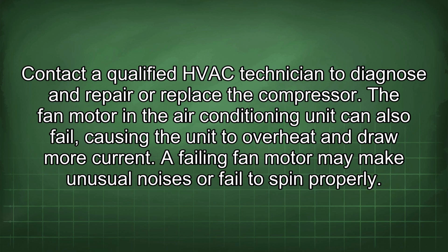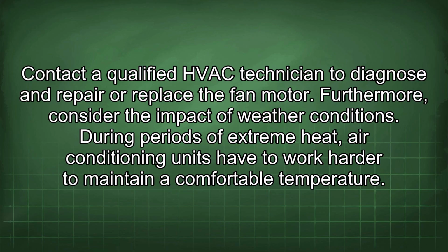The fan motor in the air conditioning unit can also fail, causing the unit to overheat and draw more current. A failing fan motor may make unusual noises or fail to spin properly. Contact a qualified HVAC technician to diagnose and repair or replace the fan motor.